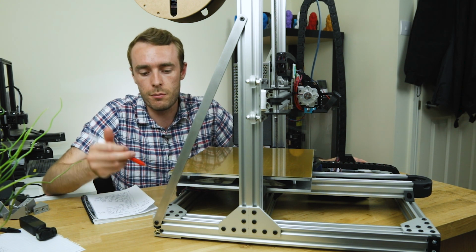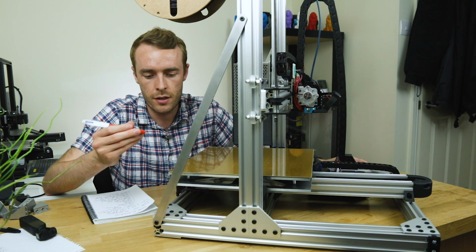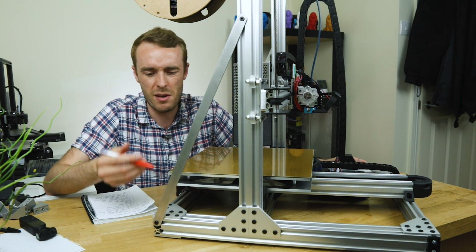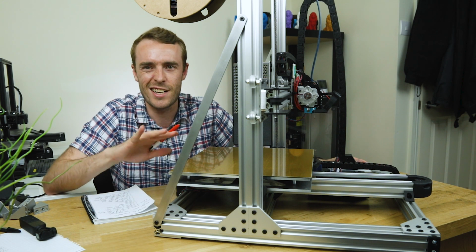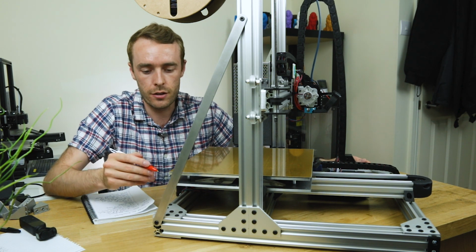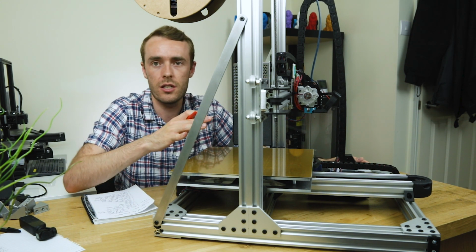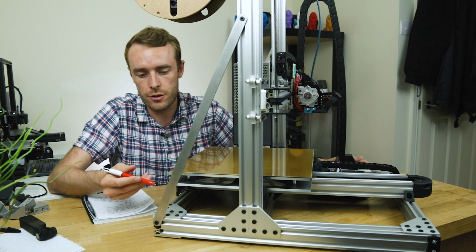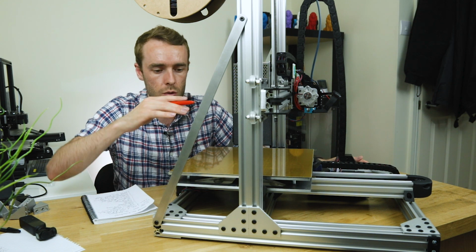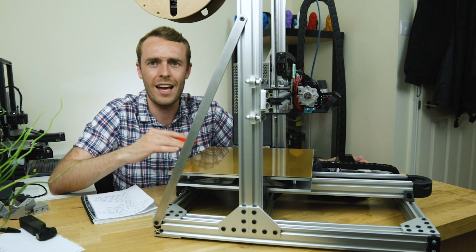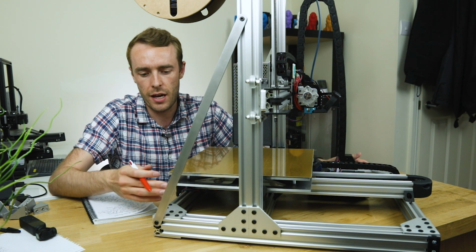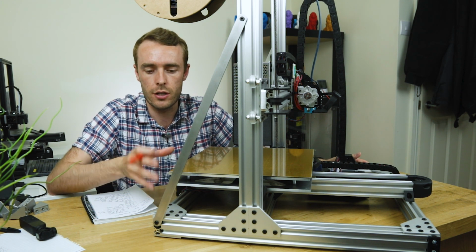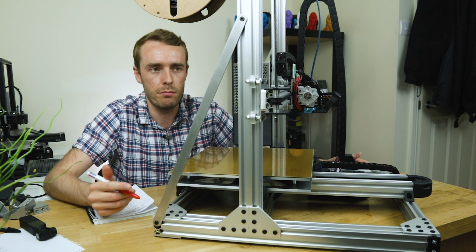So the reason for the bottom plate being 6mm thick is to have high rigidity. You need the rigidity, maybe not quite this much, I didn't actually calculate it to be fair, but the reason you need high rigidity is with this large build volume, you can put a lot of material into it. And so you obviously don't want your Z height to change after adding all of that material. So by having a rigid plate at the base, you can reduce the amount that it's going to bend as a result of the built material.